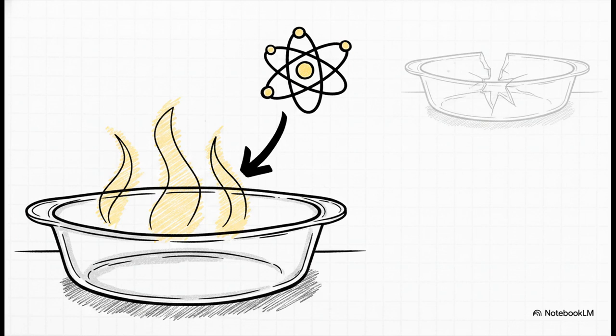So how do engineers combat this? By chemically altering a material's properties to lower its expansion rate. Take standard soda-lime glass, for example. It has a high expansion coefficient and shatters super easily under rapid temperature changes. But by adding boron to the mix, engineers created borosilicate glass. You probably know it as Pyrex. Its expansion coefficient is roughly 3 times lower, which drastically reduces those internal stresses and ensures your baking dishes don't explode when you yank them out of a hot oven.